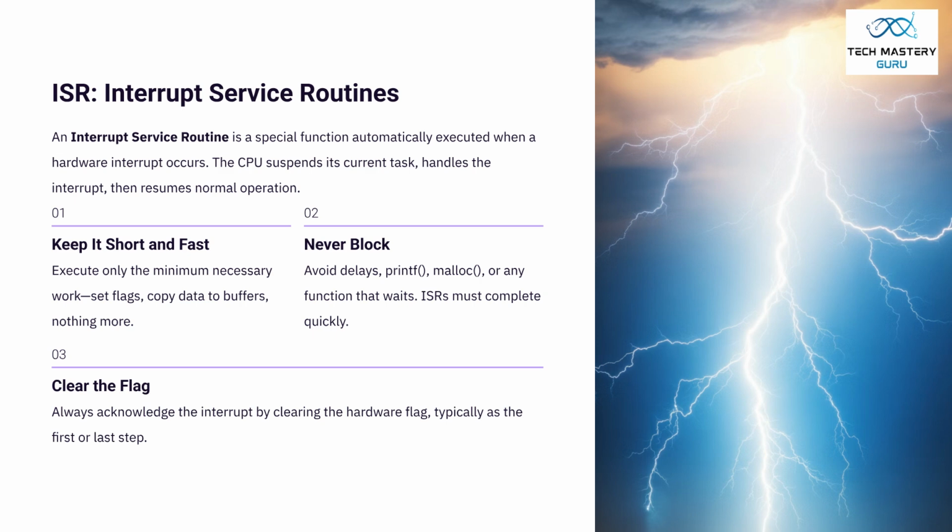An interrupt service routine, or ISR, is a special function executed automatically when a hardware interrupt occurs. ISRs must be kept short and fast, avoiding blocking operations like delays or dynamic memory allocation. Always remember to clear the hardware flag to acknowledge the interrupt.